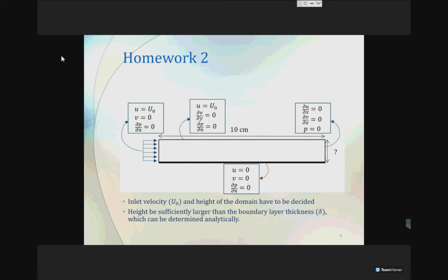So if we are fixing the pressure over here as 0, there must be some additional pressure at the back, but because our problem is an incompressible one, this pressure is not going to have much of an effect. The value of pressure is not going to affect our problem because we are considering an incompressible problem. Anyway, hopefully all the boundary conditions are clear, and now we can move forward.